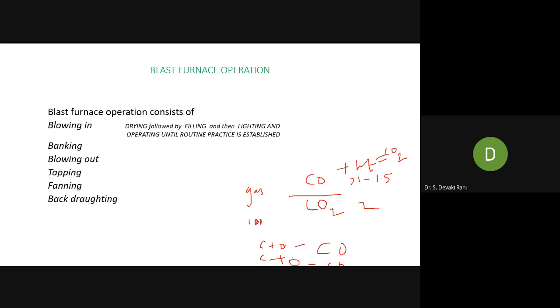This gas is taken to the blast furnace stove, where again air, with the help of a burner, you are burning the carbon monoxide to carbon dioxide. That heat is coming out. The carbon dioxide heats the refractories and is let off into the atmosphere. Then cold air is passed. It takes the heat of the refractory bricks and the hot air is passed into the blast furnace. Always remember, hot air is passed into the blast furnace because air supplies the oxygen for combustion of the coal.